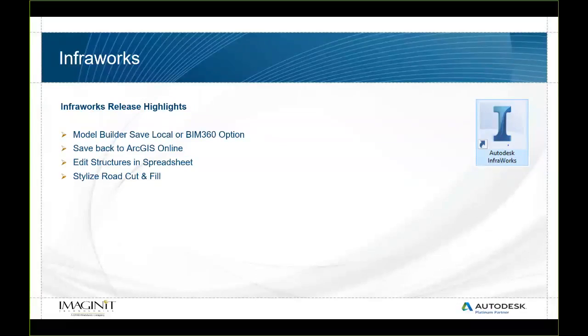One of the big changes, or one of the big things that I really appreciate that they fixed, was the BIM 360 connection with Model Builder. So if any of you had been working with Infraworks over the past year or so, when they built that BIM 360 option into Infraworks, if you were part of a BIM 360 project, your Model Builder was limited or restricted to BIM 360 only.